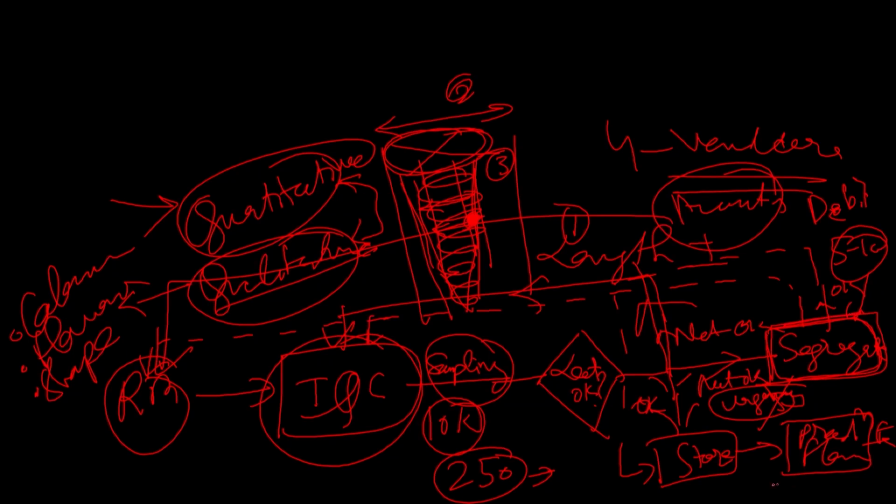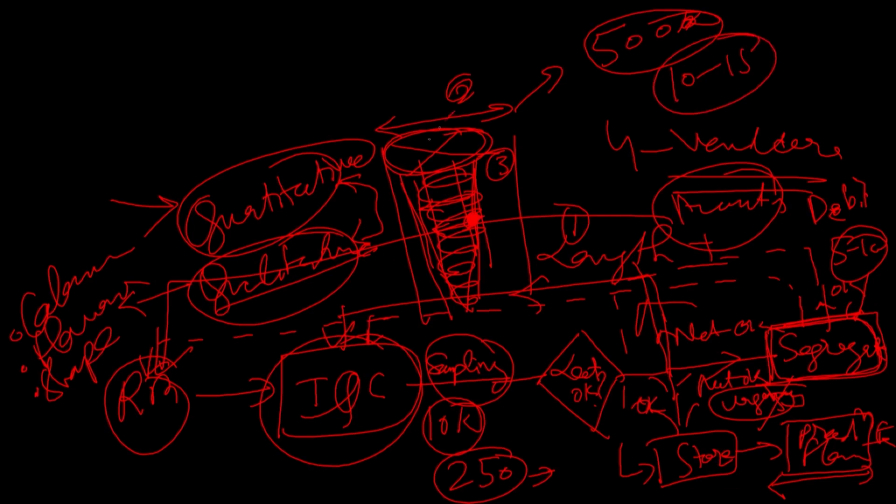Then on the production line, you accepted the lot and you start producing the product, but somewhere you see that every time you are using 500 screws, somewhere around 10 to 15 screws you are getting, sometimes the cap is not there, sometimes threads are not there, and you could not catch that in your sampling, sometimes the shape is deviated.